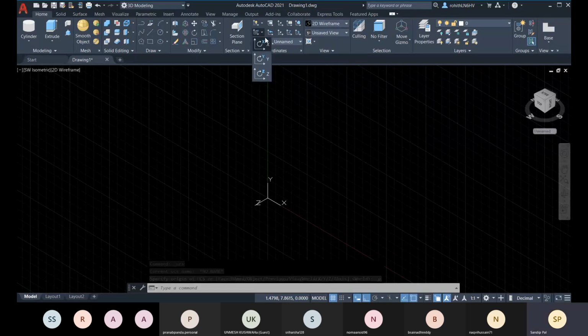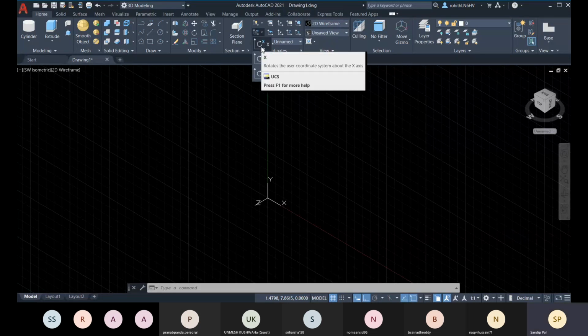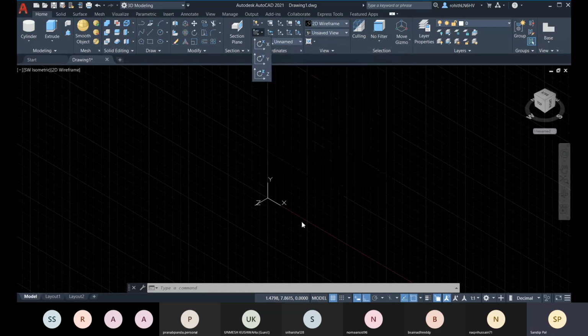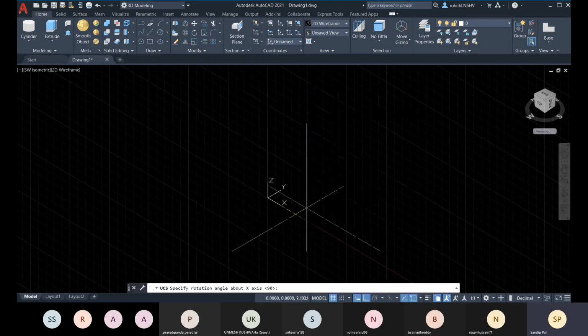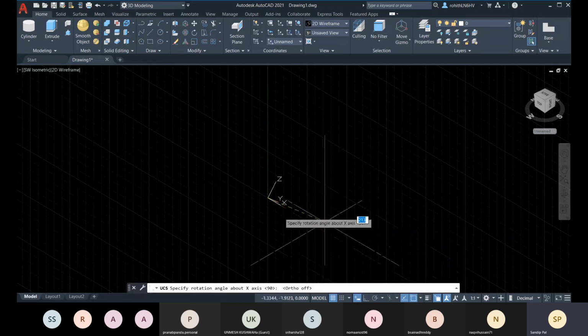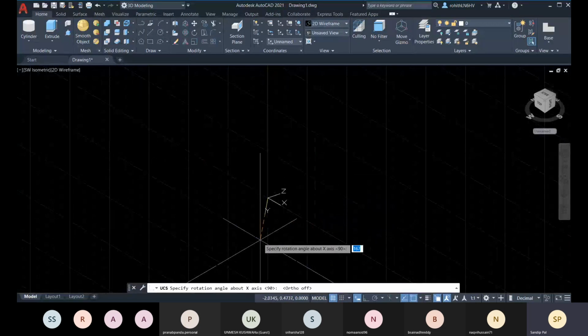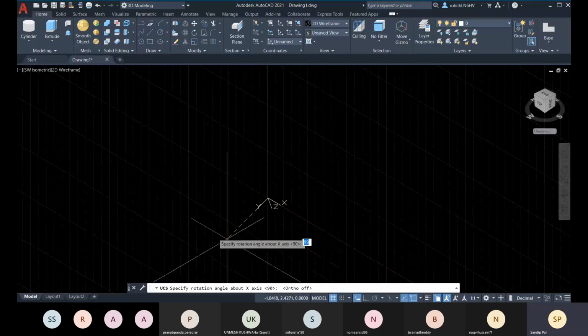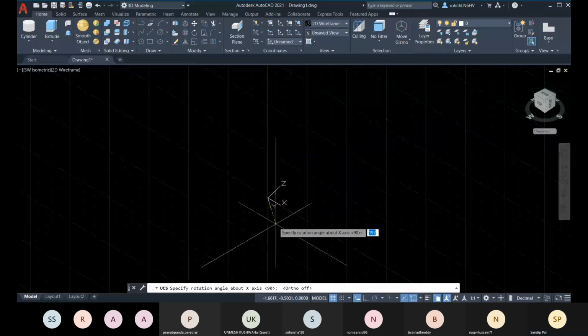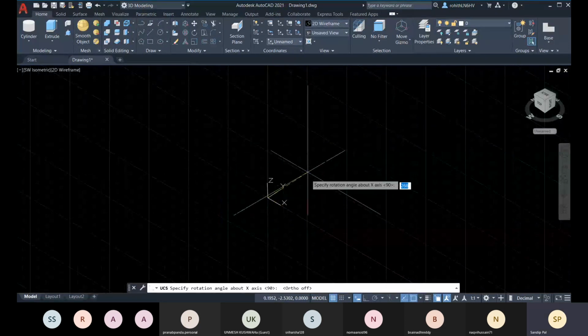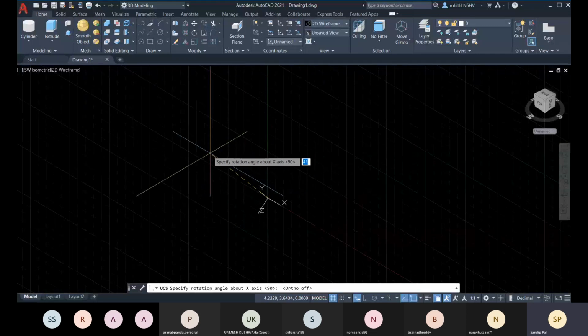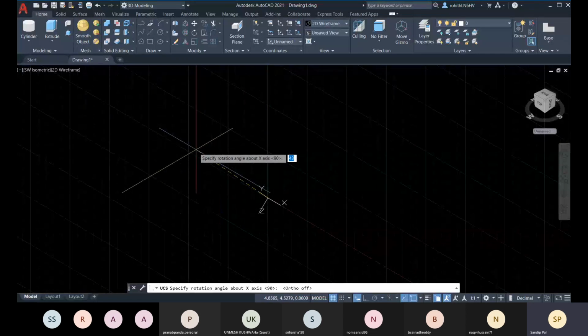And now you can choose X as axis for your rotation. Okay, X will be the axis and based on this X axis, the other two axes will be rotated and positioned. Now let's choose X and let me change. Now you see that X is the rotation axis right now and the other two dimensions you can see are rotated and you can change the position and there you can specify the angle, right?